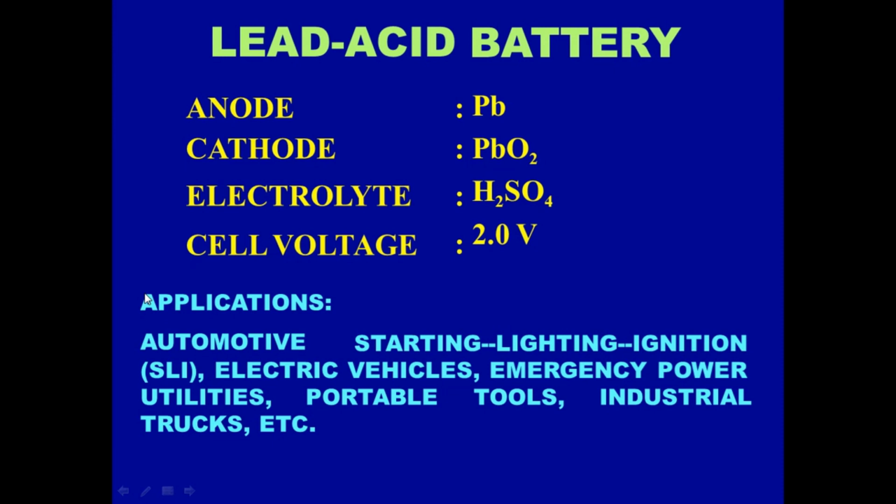And in lead acid battery, we have a vent. The purpose of the vent is to provide access to the plates of the cell, which is used to fill up the electrolyte or for the inspection of the internal condition of the cell. The vent is also used to exhaust the gas generated in the cell to the atmosphere. During the chemical reaction, there will be some exhaust gas produced, and this exhaust gas can be taken to the atmosphere through this vent plug.